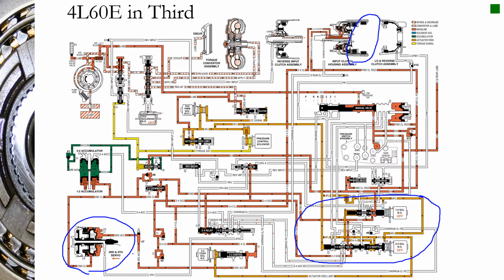So we'll actually look at some of the issues, like they've got this accumulator check ball right there that has a potential of leaking, and we'll look at the accumulator, or the accumulation really is done by the servo when fluid pressure enters that circuit. So we'll focus on those topics there.